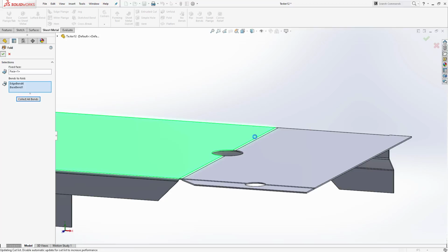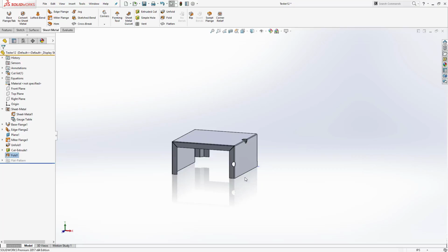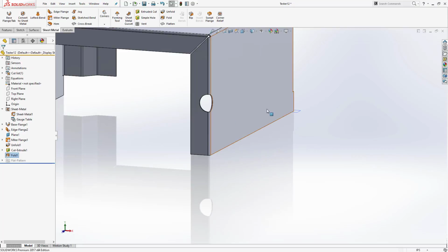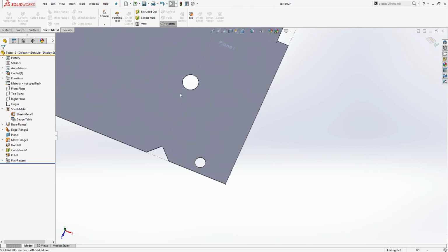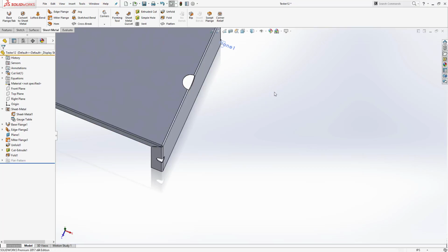Then we go ahead and click OK. Then we're going to have those two cuts on those corners without really having to do too much issues. So when we actually go to our flat, it's that accurate circle we were actually looking for instead of kind of that stretched oval. So if you're having issues with that, that's that quick way of kind of fixing that issue.